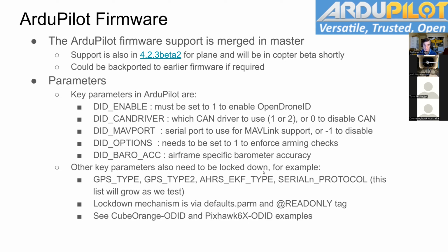The mechanism we're using for that is a lockdown mechanism via the default parameters file for your particular board and the read-only tag. What that means is that a vendor who wants to comply with the FAA's remote ID requirement with ArduPilot is going to have a custom firmware. You cannot use the click-in Mission Planner install of standard CubeOrange firmware. That will not be compliant. Instead, what I've done, and I'll just stop sharing for a second and I'll show it in my editor.